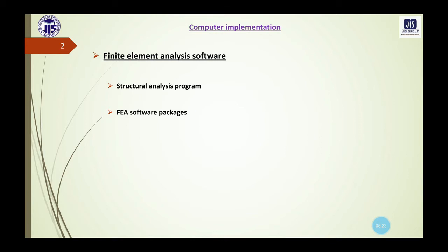Now the static analysis is carried out by solving the equations of equilibrium, which is followed by the computation of the stresses. But in case of dynamic analysis, there are various options available, like frequency calculation only, then frequency calculation followed by response history analysis, then frequency calculations followed by response spectrum analysis, and the response history analysis by direct integration.